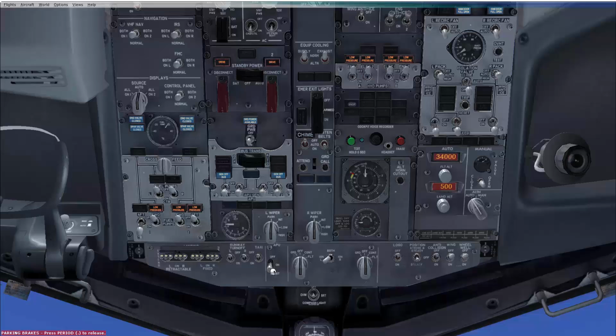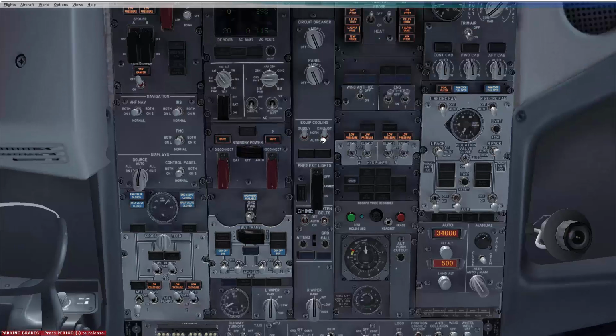Alright, you see the RPM gauge for the APU is starting to settle back down from its initial ignition, and it's going to settle on a constant speed, and very soon, there we go, we have APU power available, and we're on the APU bus. APU bleed switch on, voltmeter select, APU. Make sure that the APU is actually generating power for us.